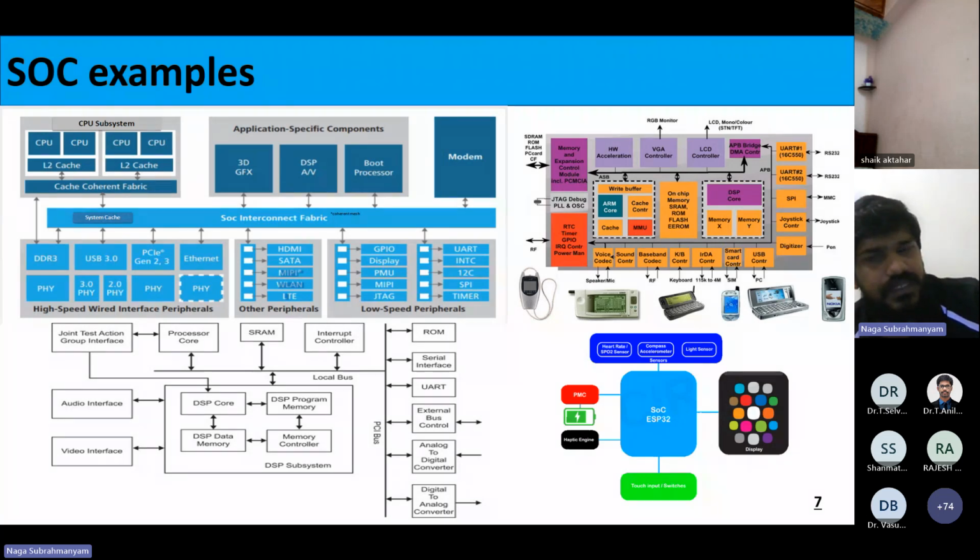So here verification is again of two aspects. One is, is it really necessary to purchase the third party VIP? It depends on the designer's interest. If the designer wants to verify how this SPI is working on this SOC, we will verify this at the system level. Sorry, not system level, SOC level. If they have their own SPI design, we can verify it at both levels, IP level and subsystem, meaning top level.